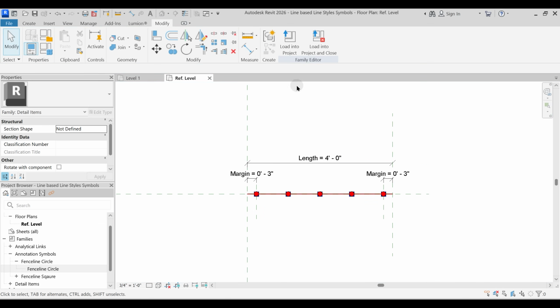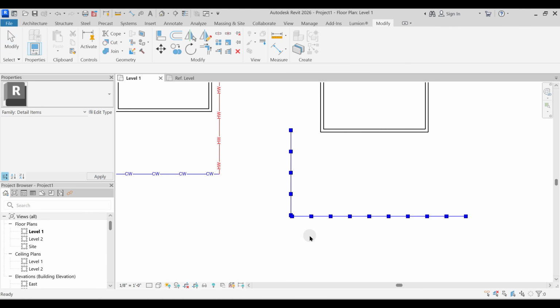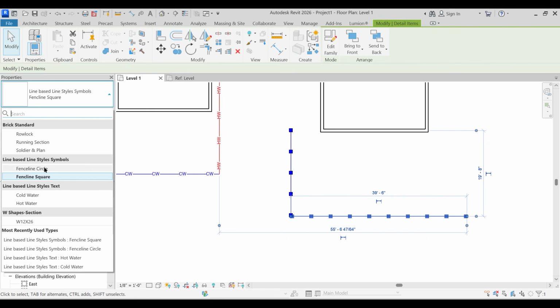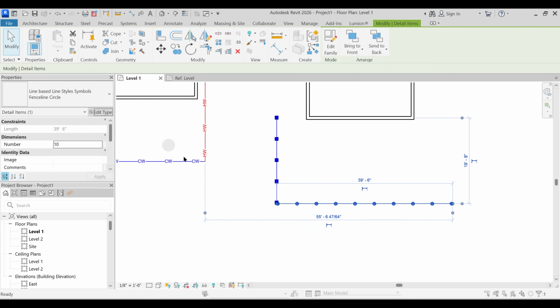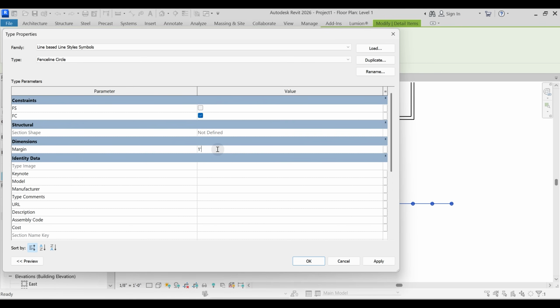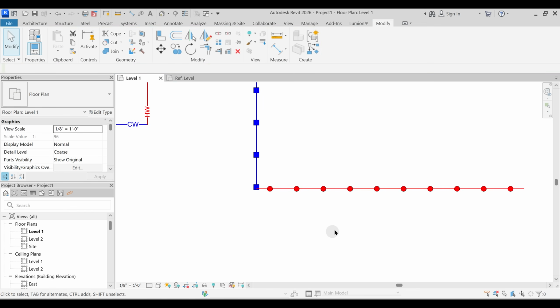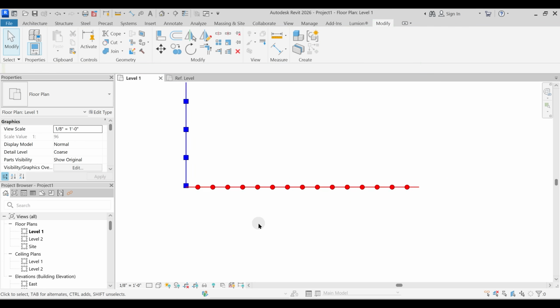And just say HR and load this back into the project, override existing version and parameters. So now if I change this to, let's say, fence line circle, yeah, see, we got it perfect. So within parametric modeling, there is only the issue of locking and constraining it. That's it. Okay, so see, now within this, you can make it equal to 5 and make this equal to 15 or whatever you want.